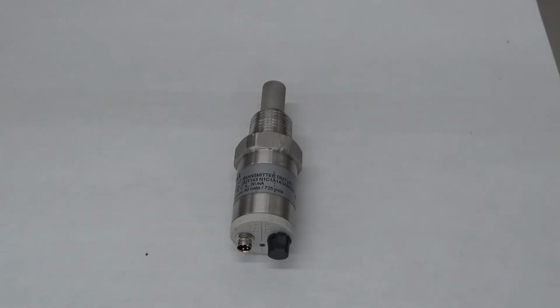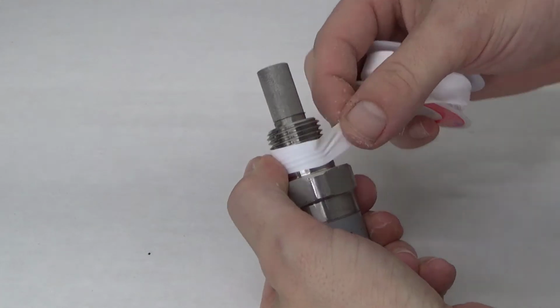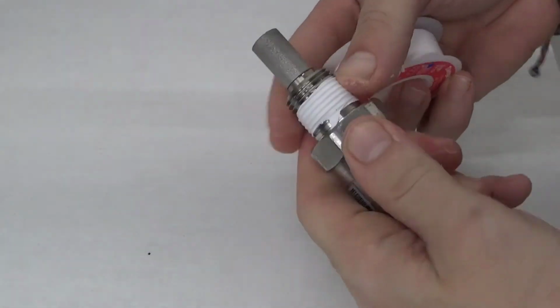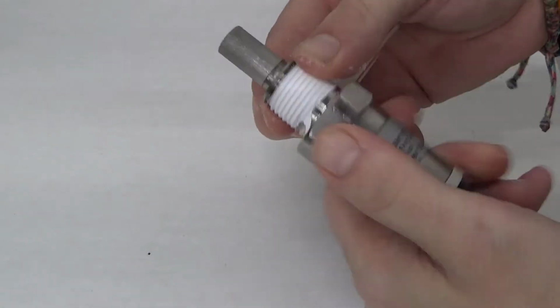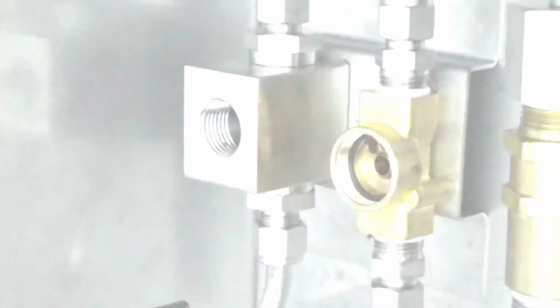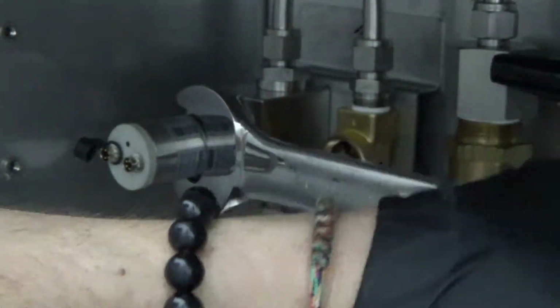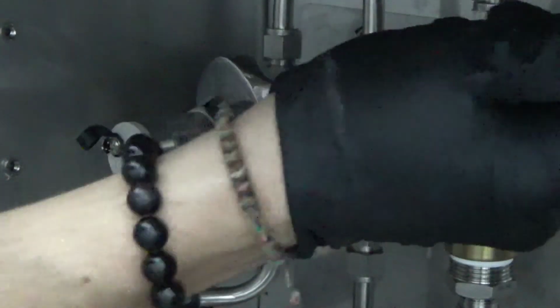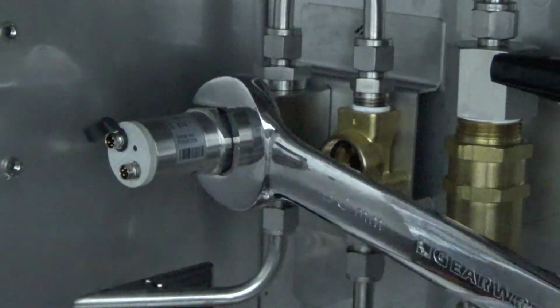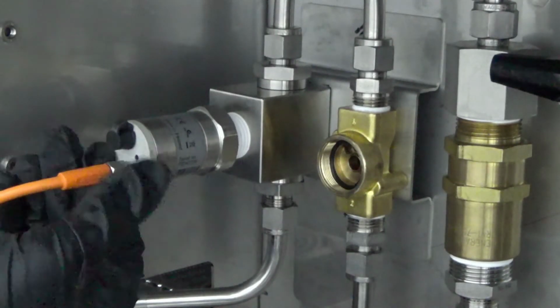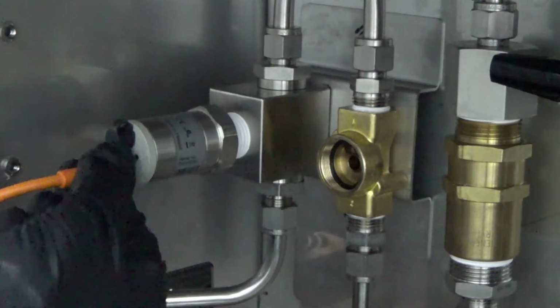Once we have reinstalled our pipes, we will now reassemble the moisture sensor and exhaust solenoid. To begin this process, we will first verify that all old pipe tape has been removed from the threads. Then, we will apply about 2.5 to 3 full wraps of new pipe tape, making sure not to get any of the tape on the first threads of the connector. We can now reinstall the moisture sensor and use our 30mm wrench to tighten. We want to make sure we match the torque that had been applied previously. Once properly tightened, we can reconnect the moisture sensor cable.